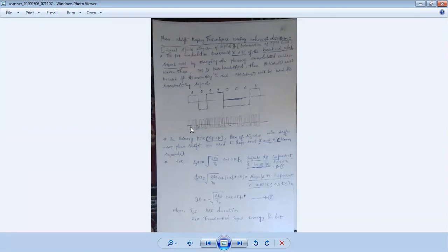Depending upon the information, we will change the carrier wave. Look back, the frequency of this will be the frequency of the carrier. The phase, sorry, the phase for the bit changes as soon as there is a transition from 1 to 0. So whenever the bit changes from 1 to 0 or 0 to 1, the phase shift will change. The phase of the carrier will be changed.